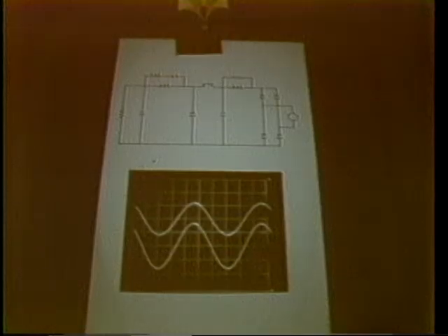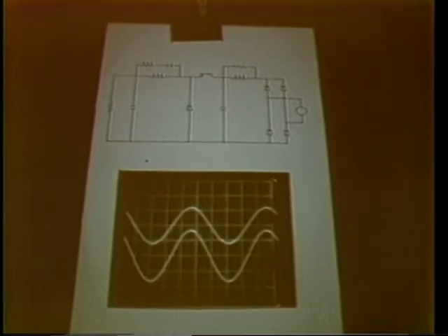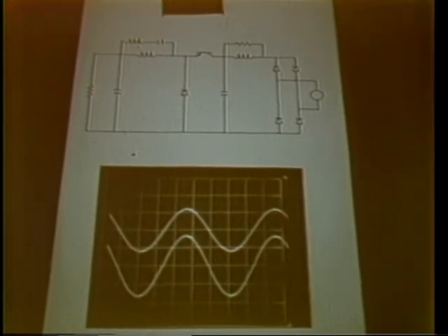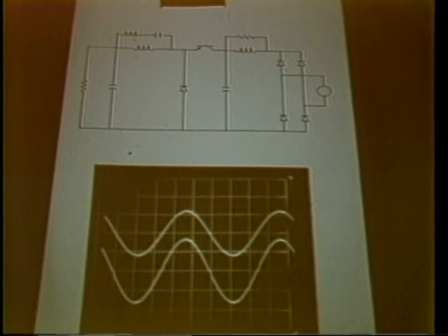This next slide shows the addition of a high-frequency modulating stage, which creates the sinusoidal line current shown in the lower trace in the photograph. The transistor is switching at 20 kilohertz. It's controlled by a microprocessor using a switching pattern stored in RAM.